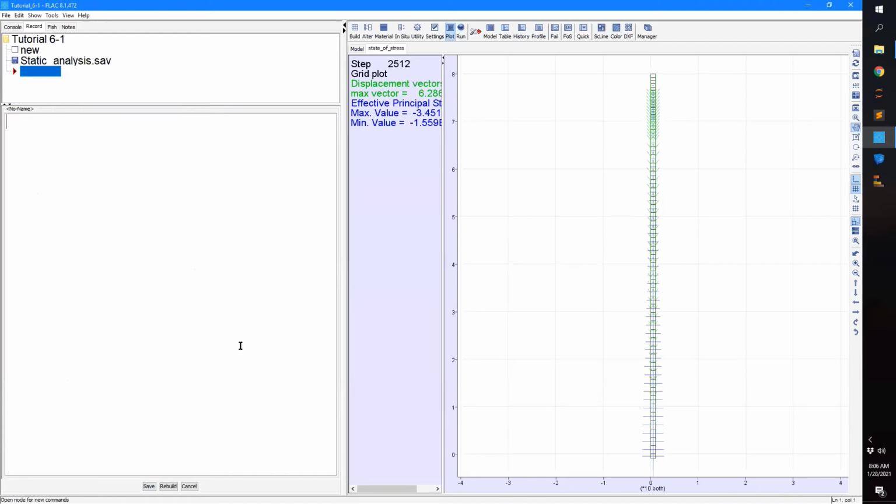Okay, a few things that we want to do. First up is that although I suspect that the velocities should be quite low, we might as well zero our velocities. So we can reinitialize our velocities as 0. We could go to the in situ, then initial, or alternatively, we could just initialize x velocity as 0.0, y velocity as 0.0, and then rebuild.